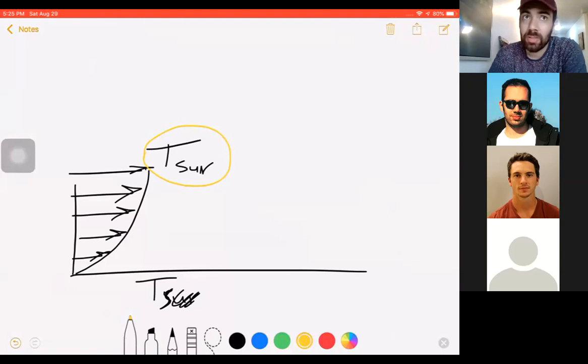That is because if you use the temperature that is still inside your velocity profile here, this temperature is actually changing from the surface to the surrounding. So you have to put a temperature at a location that is far away from your surface, that the surface is not affecting. That's what it means.